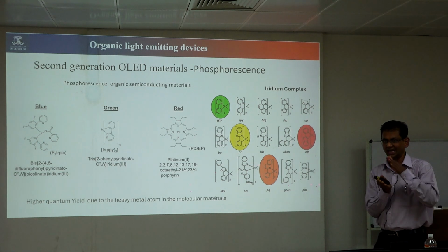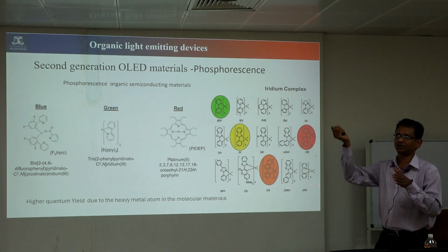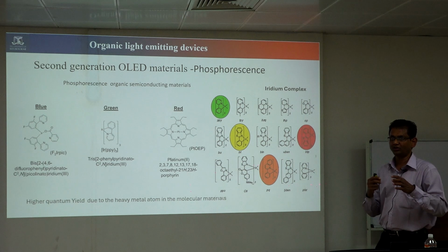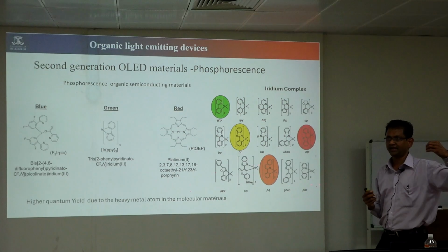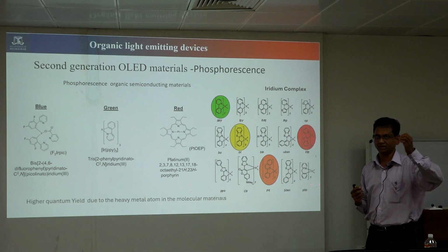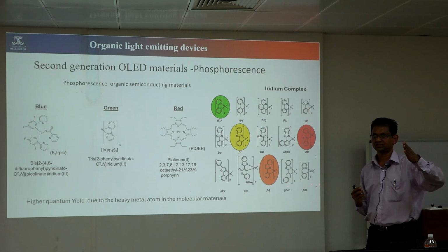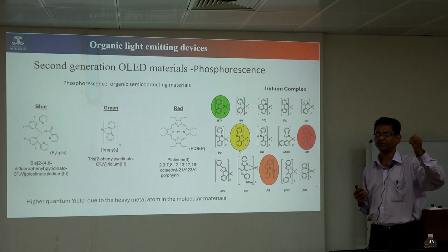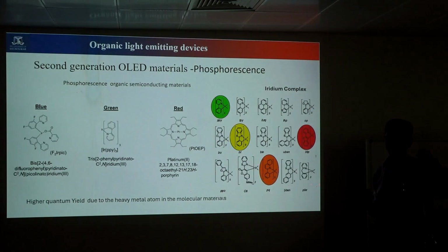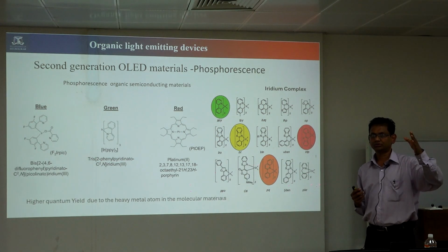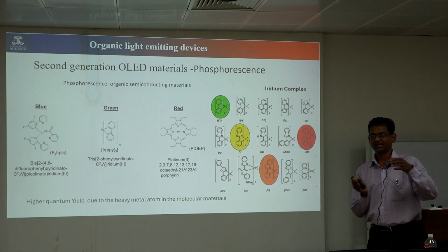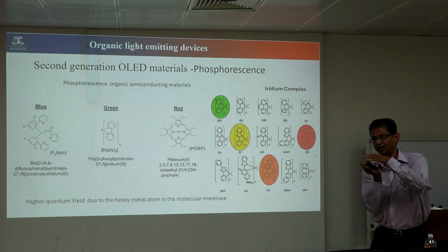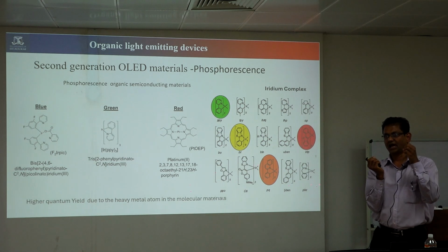The photon is actually absorbed by the layer and how many electrons are given, that is called IQE. But EQE means the total influx, because with the total influx, some of the radiation will be lost because of absorption by the hole transporter, electron transporter and glass; everything will absorb something. That is not taken care of in the EQE calculation. But in IQE calculations, those stray absorptions are subtracted, so that exactly what got absorbed and what was generated is counted. That is IQE.